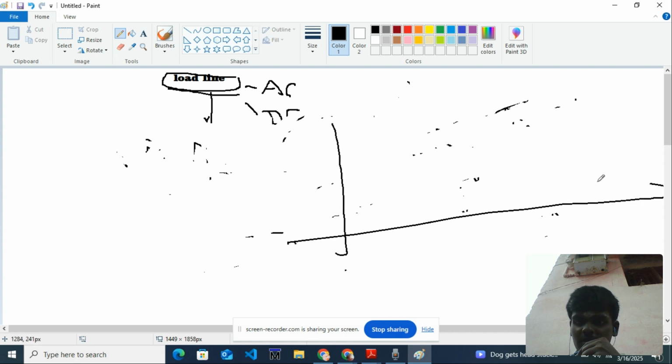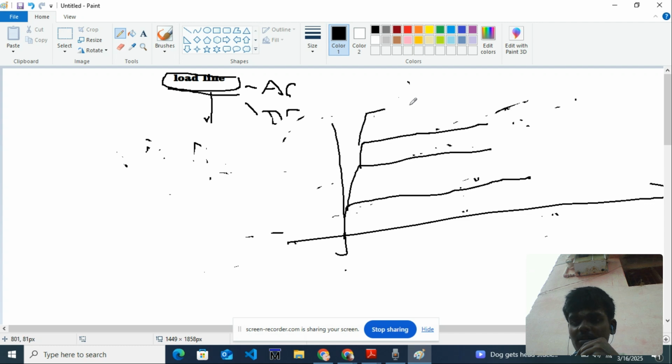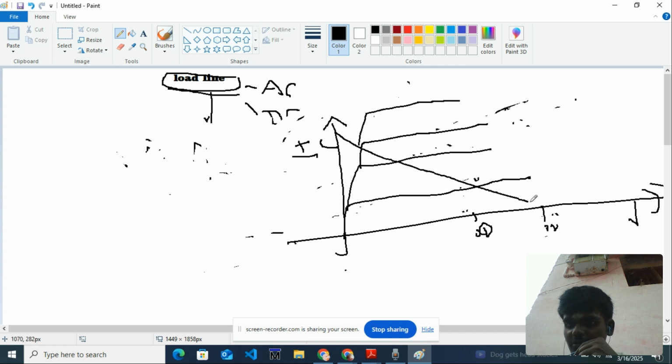You draw the graph the same way. Now you all may know IC, and this is V. So the DC load line you take from the part here, something like 10 to 12, the line from IC to this cross line will be a DC load line, and the meeting point will be called Q. This Q point will later be measured by the AC load line.